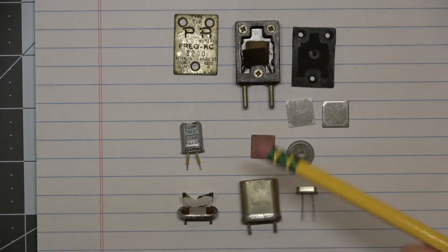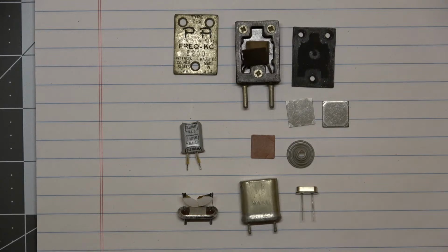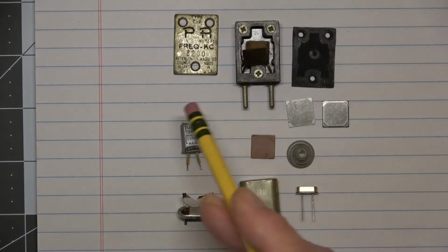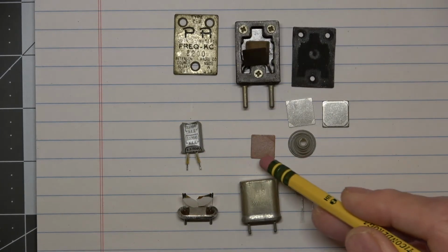And in those good old days, hams would actually take one of these apart to expose the quartz crystal, and they could use a lead pencil to slightly lower the frequency of the crystal. Or they could use toothpaste to abrade it to take it higher. Yep. So hams actually were adjusting the frequencies of their crystals that way. So that's something that none of you will need to worry about.